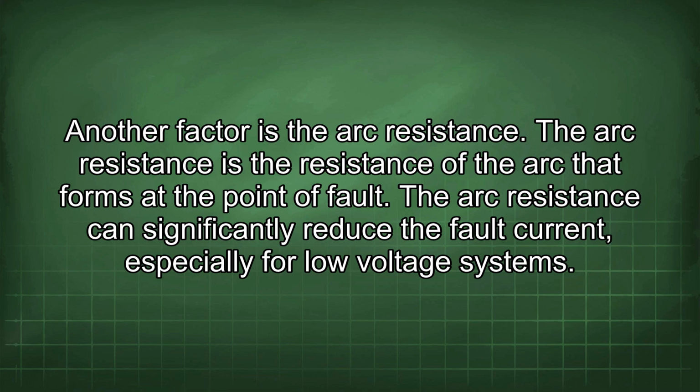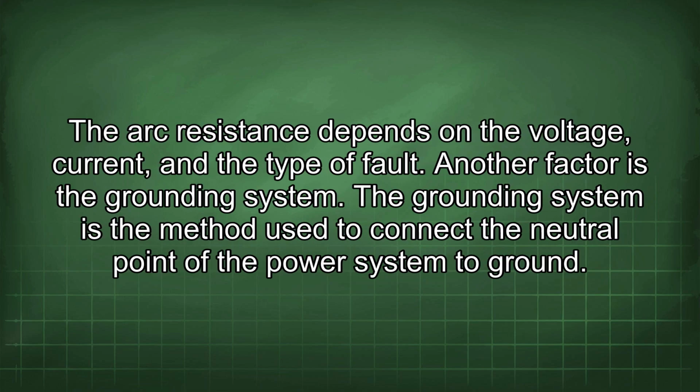Another factor is the arc resistance. The arc resistance is the resistance of the arc that forms at the point of fault. The arc resistance can significantly reduce the fault current, especially for low voltage systems. The arc resistance depends on the voltage, current, and the type of fault.